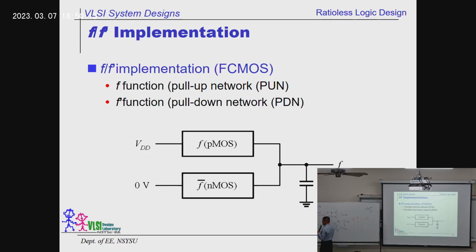As we said yesterday, an N transistor is used to pass a low signal well, because it is good for discharging. So when both of these inputs are 0, this one is on, this one is on, and here both of them are cut off. So there will be no discharging path.